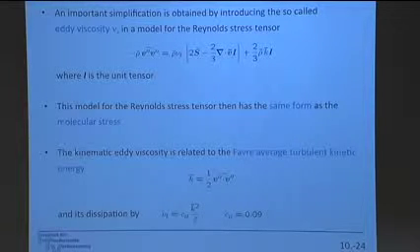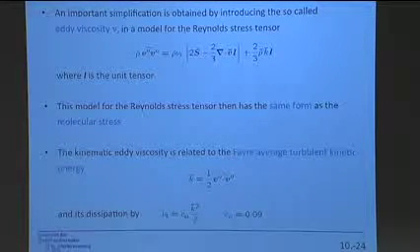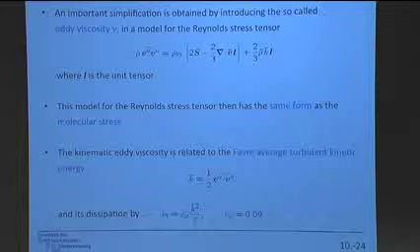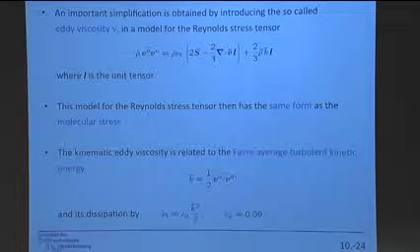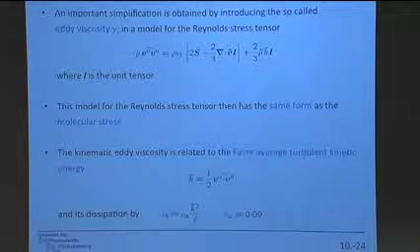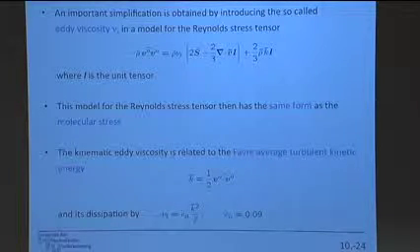The square root of this would be a velocity scale, and now I need a length scale, and I can get this in different ways without giving any reasons. You can also get a scale from the so-called turbulent kinetic energy dissipation rate, and that then leads to the k epsilon model. Now, epsilon is the dissipation rate of turbulent kinetic energy.